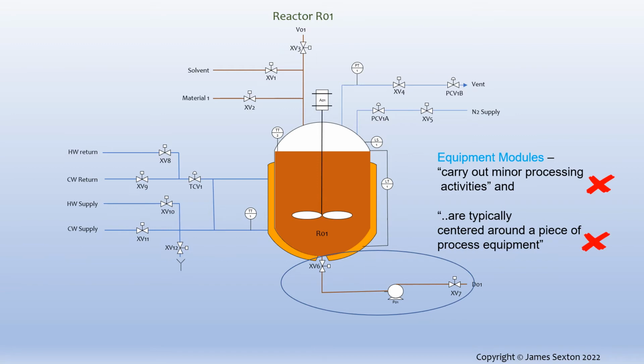No. Normally, to define a unit or equipment module, there must be some container where processing can take place. There are some exceptions where processing is done in line, like forms of filtration or a batch totalizer. Once again, the vessel is the only place that any processing can take place in this scheme.